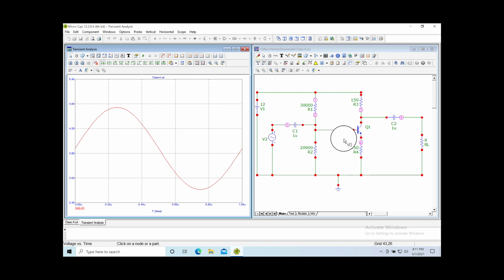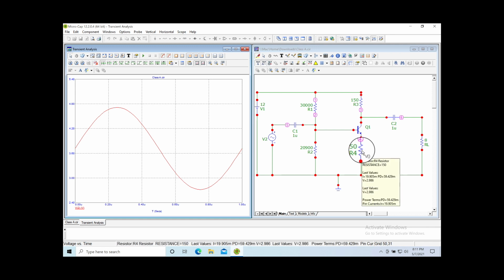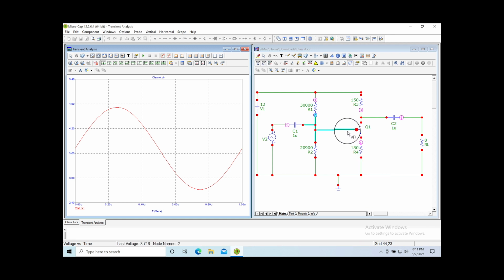Now, just to give you a little tip, remember the base current doesn't take a lot of current to drive this current. So from this point, if you're looking into the base, you're seeing a little bit of current go through there, but you have 150 ohms and you have a lot of current. So really that resistor looks like a big resistor to this base. That's because the gain of the transistor affects that. So really that resistor is the gain of the transistor times this resistor.